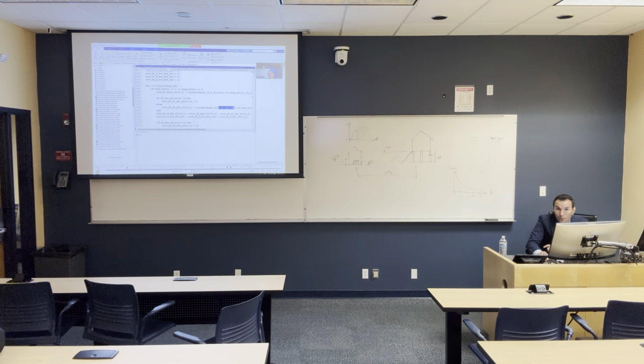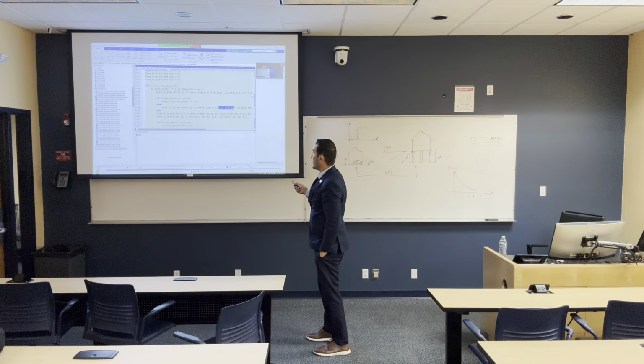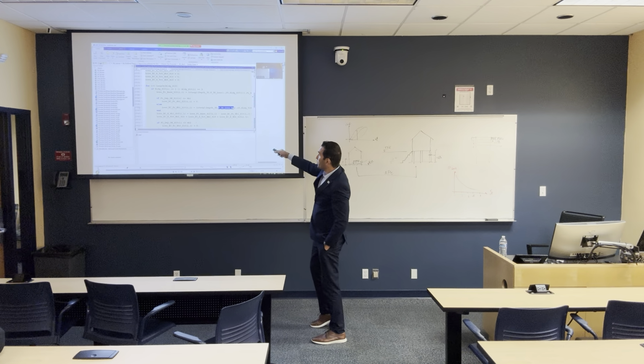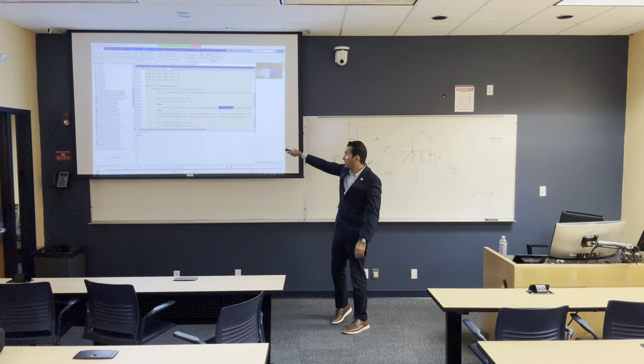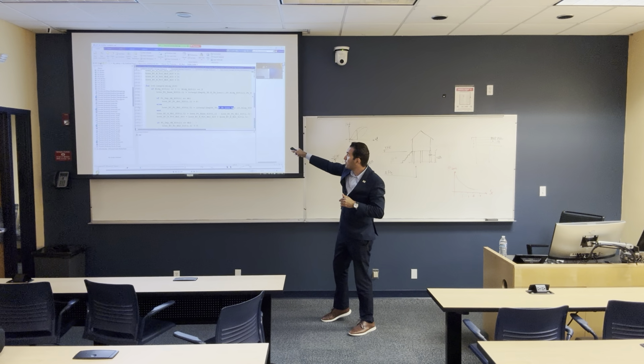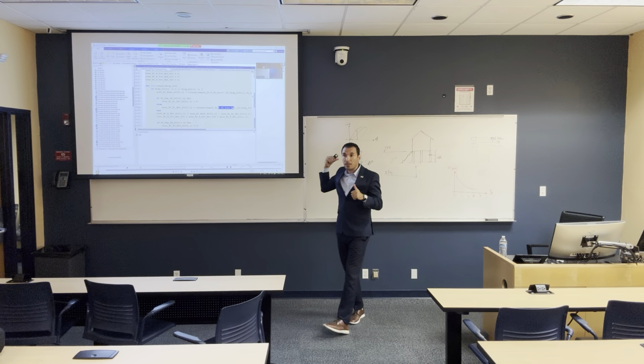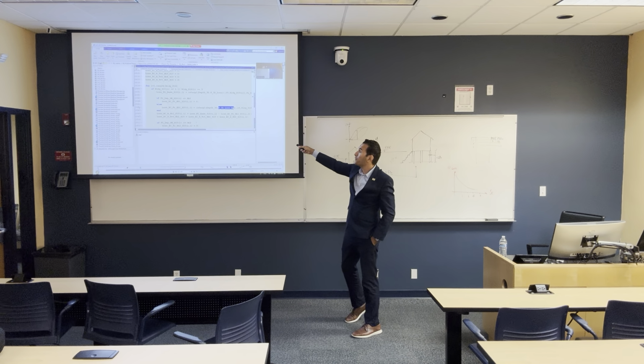But let me tell you something. I did one mistake. Do you know it? When I did the find and replace, I replaced all the 3D losses, but I just want to replace them here, and I don't want to replace them in the base scenario. Here I'm calculating the base scenario without any mitigation. I have here F3D loss without elevating components. But when I did the find and replace, it also changed this to F3D losses with elevating components, so I have to remove it, okay?